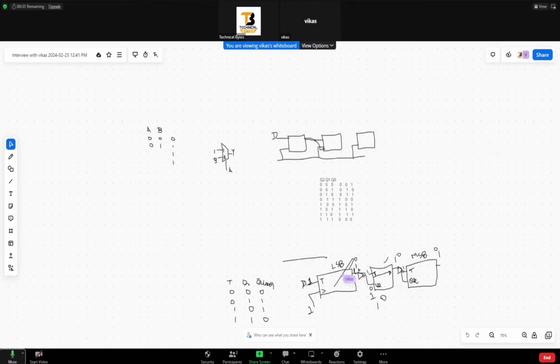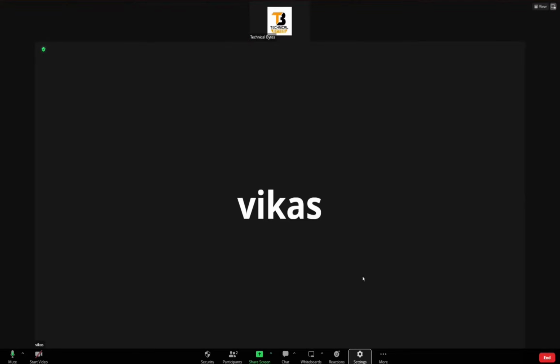What will happen at the next clock cycle? In the next clock cycle, again, since the input is 1, it will toggle. It will give the output 0. So here, since it is 0, now it will transition from 0 to 1. That is the positive edge of the clock. The pattern will be detected here. Basically, by putting the NOT gate, you will get your desired result.